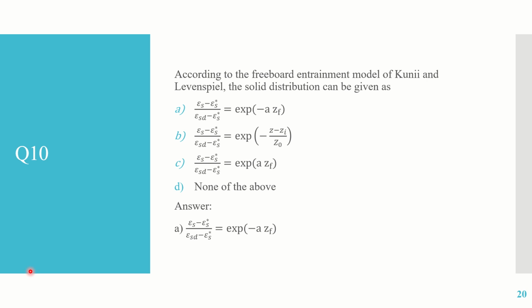So this rate at any level in the freeboard, the rate of removal of fines from agglomerates to form dispersed solid of phase 1, is proportional to the volume fraction of agglomerates at that level. Point to be noted is it is the volume fraction of agglomerates.